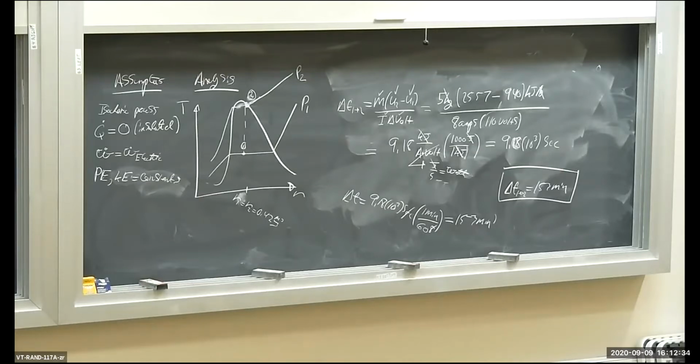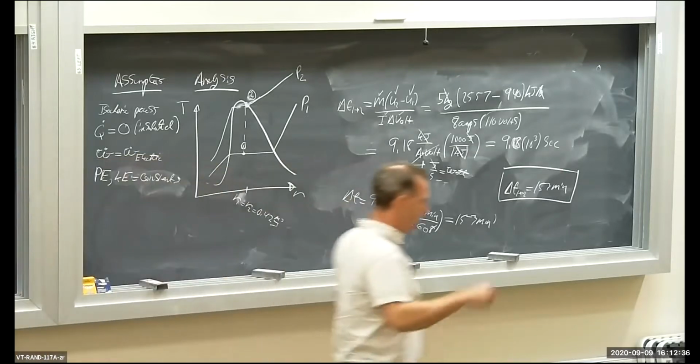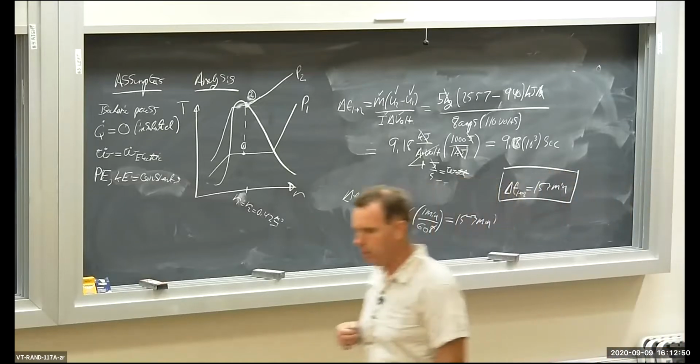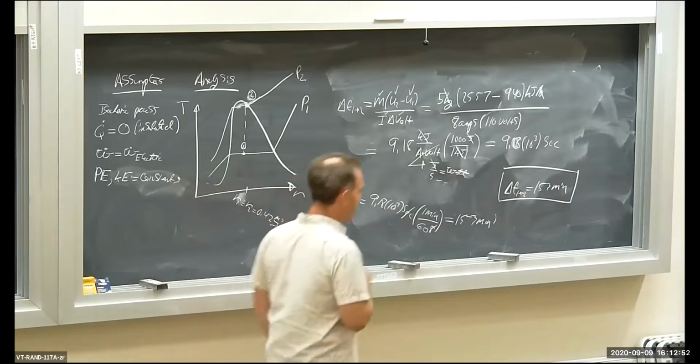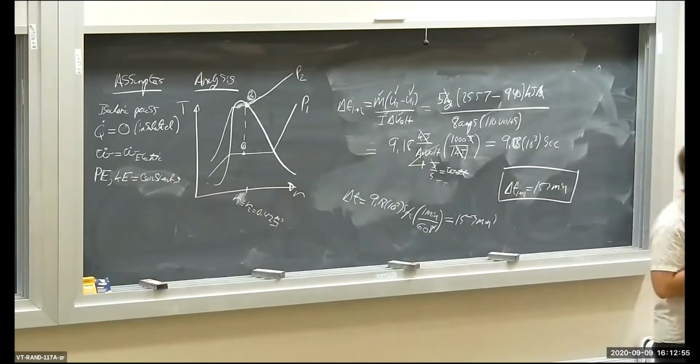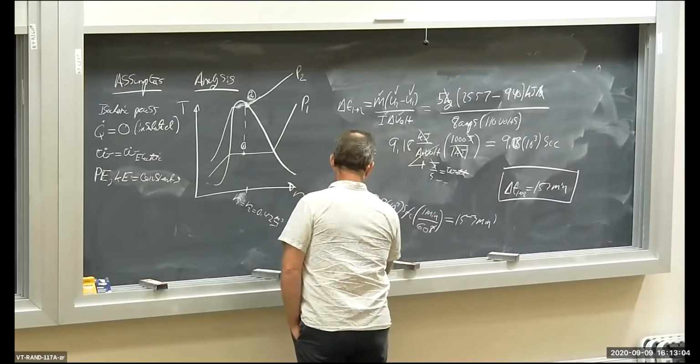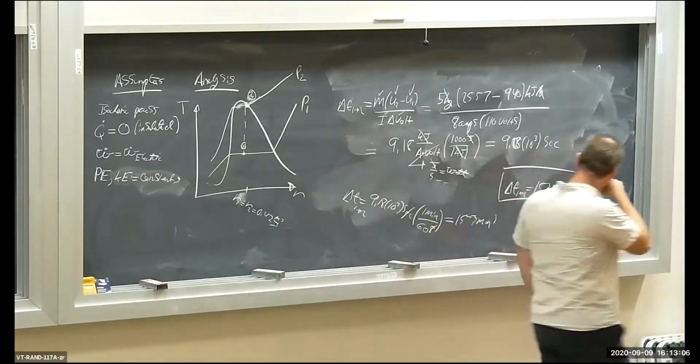This is kind of an interesting problem in the sense that we had a two-phase mixture to deal with, not an ideal gas. That complicated things a little bit. We had a quality to worry about and used the saturation tables. We also had time in this problem, so I used the rate-based energy equation and then integrated it over the process to extract delta T, which is what I'm looking for. By the way, I was calling this delta T from 1 to 2.